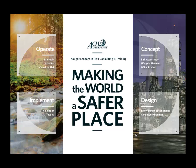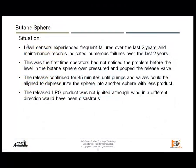So what is the situation for this butane sphere? We can start going through the HAZOP first and then go through the layer of protection analysis. The level sensor experienced frequent failures over the last 2 years, and maintenance records indicate numerous failures. So we can see here that the demand rate at this moment is more than once per year, so it is happening very often in this case.